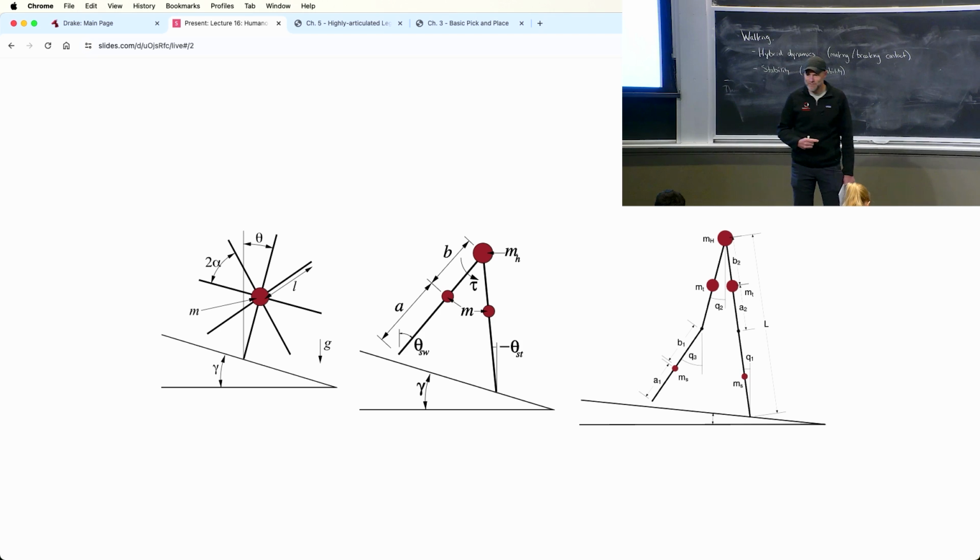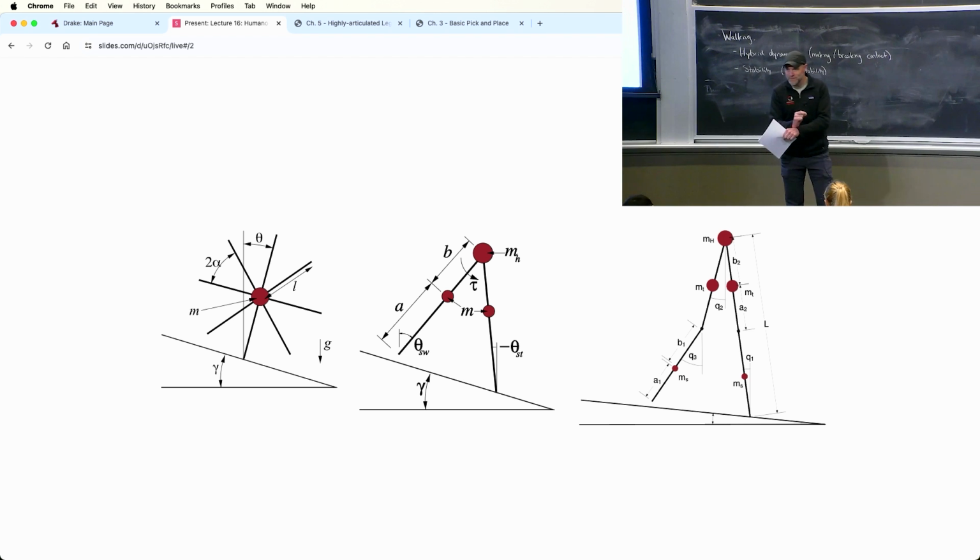So something's wrong with what I'm saying here, right? There has to be something that makes it easier again. And there is. And that's the number one message I want to send today, is that actually when you get enough degrees of freedom, things get easier again, because you can start making some abstractions. Okay? You can sort of assume that I can put my foot anywhere to begin with, and then fill in the details because you've got enough joints to figure it out later, right?